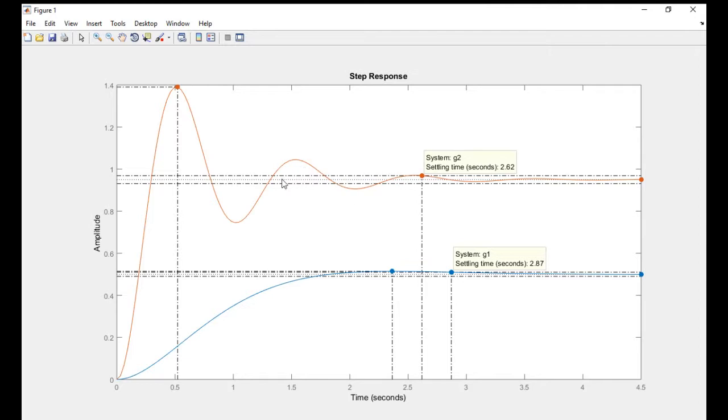If you think of the drone, just put your hand up for a while and level it, and move your hand in a similar way to what you're seeing there. That occurs in about 2 seconds. Move your hand up and down for 2 seconds. Let's say this amplitude was in meters, then the drone would have been commanded to go to 1 meter, but instead goes to 1.4 meters. So it's 40 centimeters over the required point, and it dances a bit before it settles down to that point.